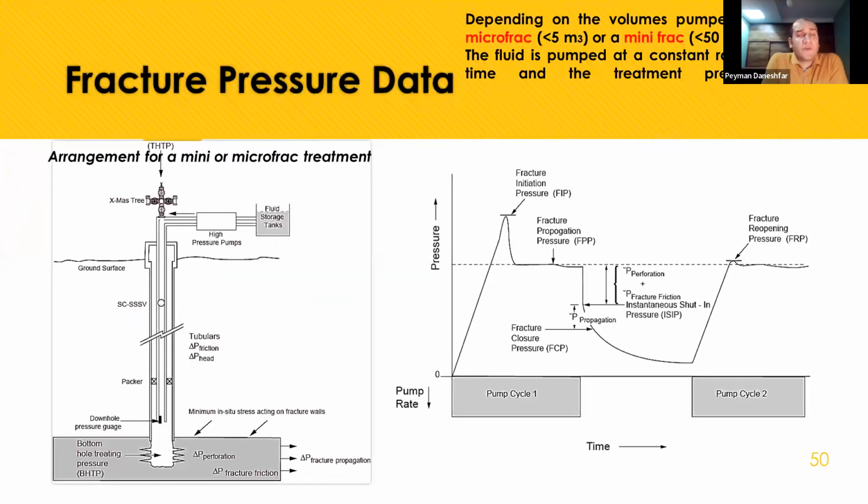How can we find the fracture pressure data? In a field, prior to hydraulic fracturing jobs, we should do Mini-frac jobs. What is a Mini-frac job? It simulates a hydraulic fracturing job, and I will explain how we can interpret it and how we do it in a job. It depends on the volume of pumping.